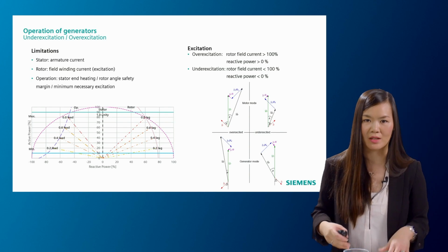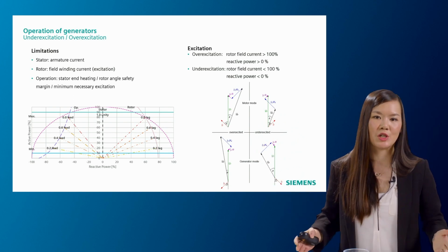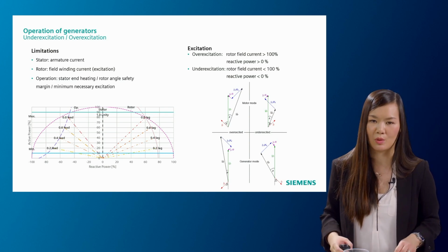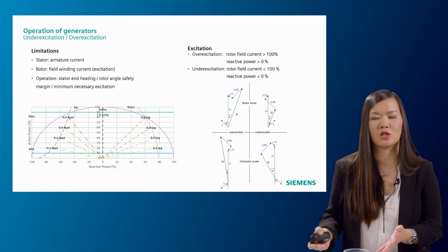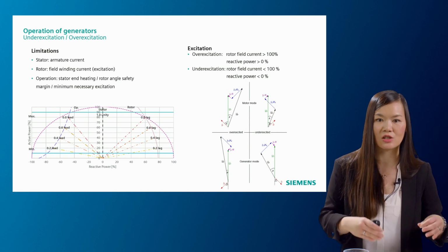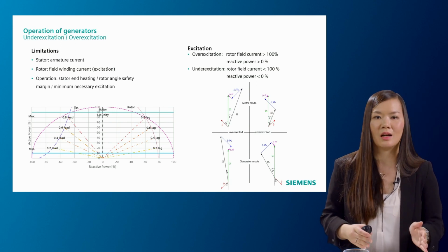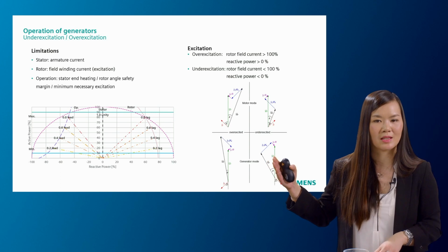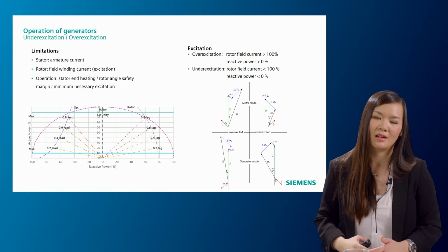And how does it look, and what is the reason behind that? You can see that in this phasor diagram I'm trying to draw. Every rotating machine can work either in motor mode or in generator mode. For the synchronous machine, you have the terminal voltage, which is where the GCB, for example, is connected. But the driving voltage for the short circuit current is the internal induced voltage, and the value of this internal voltage depends on which operating mode the generator is working in. Using this phasor diagram, you can see that in under-excited mode, the internal voltage UP right here is smaller than the terminal voltage.